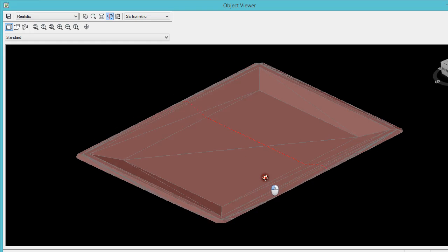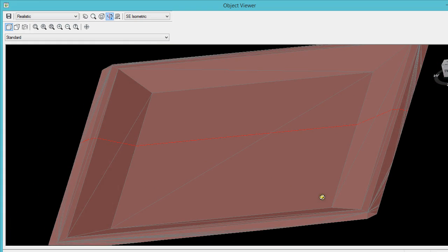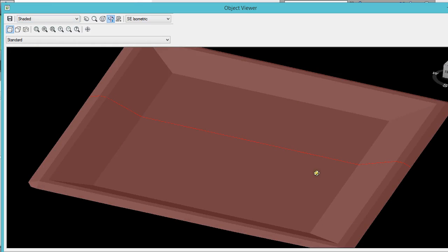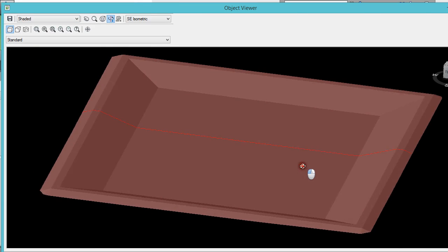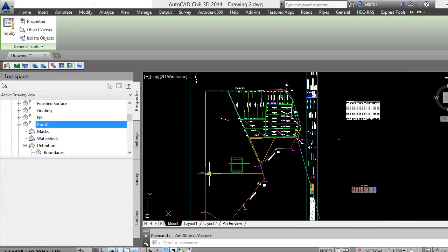I want to create a pond structure like that with any size, no structural analysis, 3 meter bank width, 3-in-1 outer toe, and 3-in-1 inner toe down to a certain elevation. Make it shaded and smooth. And with the ground, it will look like this one.